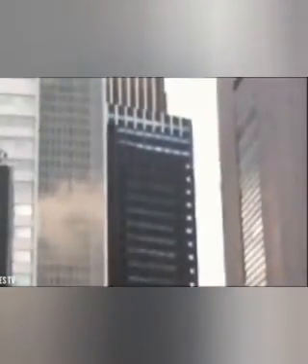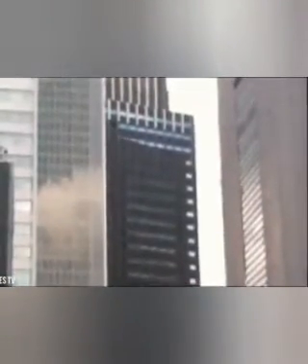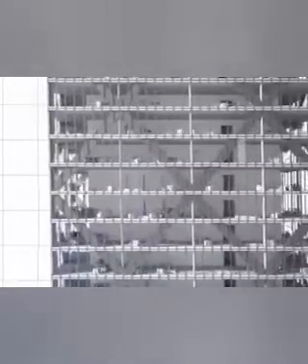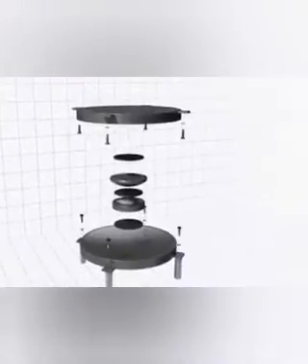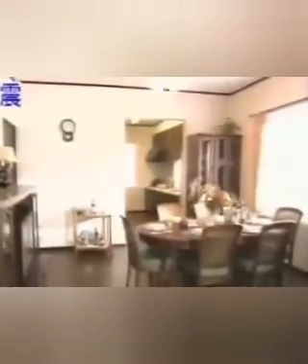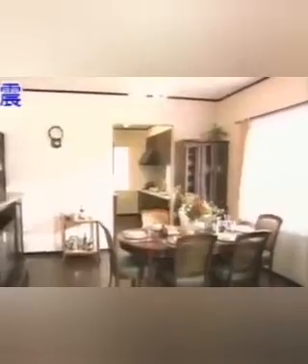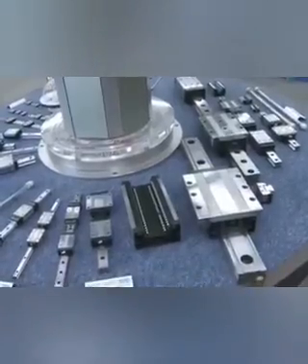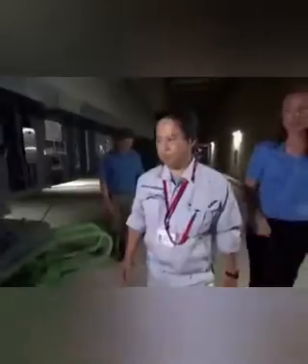If you put dampers throughout, at certain levels like every other floor, you can reduce the overall motion of the building during an earthquake to a much smaller amount and prevent widespread structural damage. Those dampers look a little like bicycle pumps, but are filled with liquid rather than air. Compressing the pump pushes against the fluid, moving it slightly and reducing the vibrations.